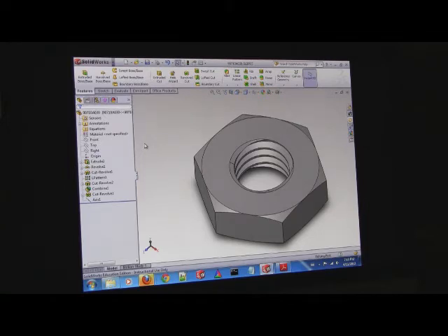Automatically goes. But now we can't see the surfaces we want. So drag this. Somehow you've already mated that. The reason was you kept doing the same mate over and over and it was complaining because it had already done it. Now you press mate, press that, rotate, and press that. And then press the green check mark.